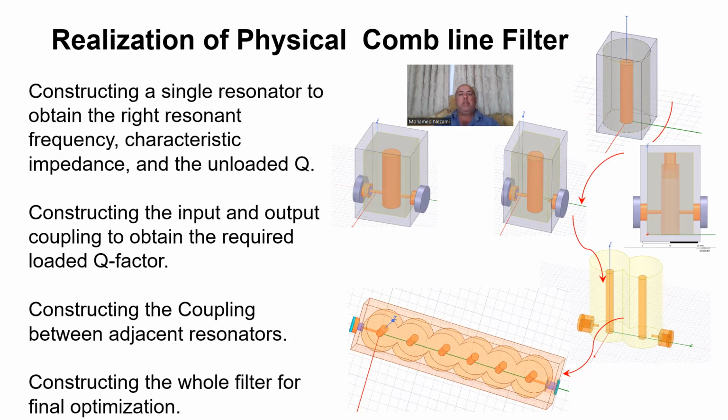tables, okay? And then you end up with a low-pass filter that has coefficients that represent basically lumped elements. And the input and output are normalized to 1 ohm usually. And then from there, you transform that onto a bandpass filter, and then you can optimize it. Actually, you can optimize it by tweaking the lumped elements in there. The lumped elements are not real, of course, because you have to replace those by resonators.